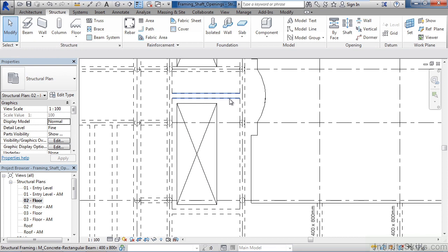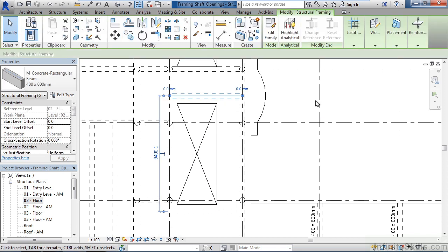Now, let's click on that first beam we placed. With it placed, maybe you would like it a specific measurement from the actual opening. So you can actually drag this temporary dimension by dragging the drag handle or the blue circle to one of the edges of the opening. From here, you can click the dimension and give the dimension a new value for the given space that you want the column to move.